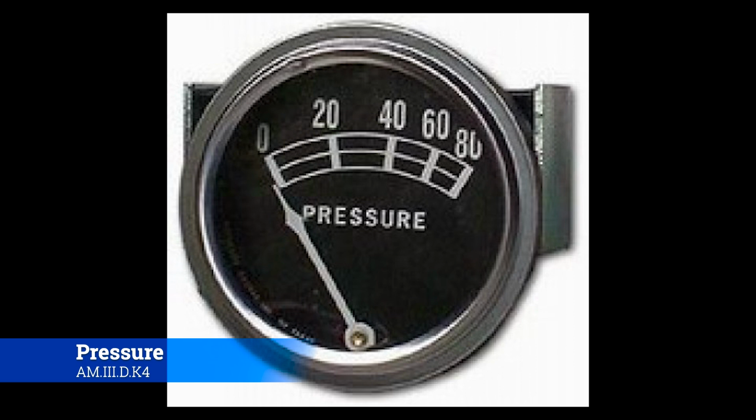If you ever watch an engine fail in flight, you'll see the oil pressure start to decline, and the oil temperature start to come up. As that oil starts to exit the engine, the pressure drops, because there's simply not enough there. Think about it like a Coke. If you put it out on a hot day, and it's full and hasn't been opened yet, you can hold that bottle and barely squish it in with your hands. But if you pour half of it out, you can grab and squeeze it, and it's not a big deal at all. Same thing with oil in an engine.